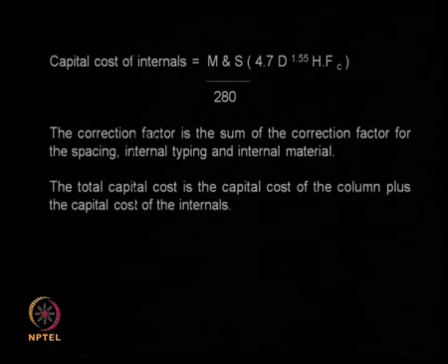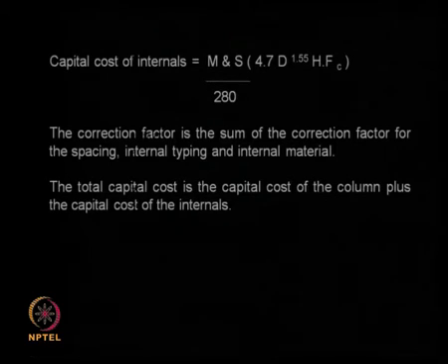So we can use that particular equation to calculate cost of equipment. So, some first order approximate costs could be obtained using these very simple formulae. Now a column extractor will also have internals, right? We can have a packing, it may have trays, it may have different types of material inside. So we need to consider that also.